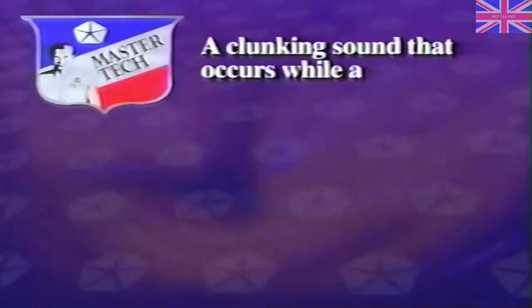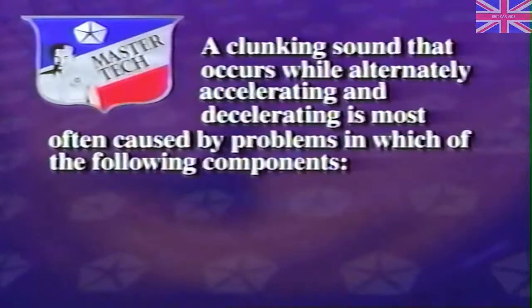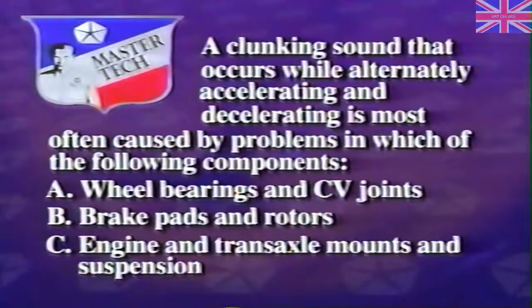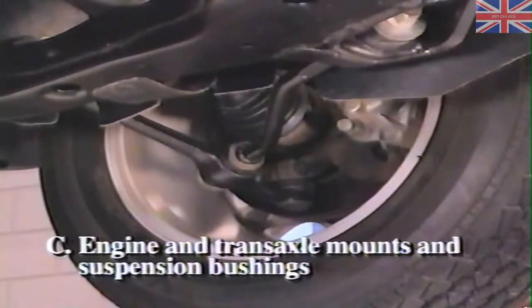A clunking sound that occurs while alternately accelerating and decelerating is most often caused by problems in which of the following components? A, wheel bearings and CV joints. B, brake pads and rotors. Or C, engine and transaxle mounts and suspension bushings. The correct answer is C. If a clunking sound occurs while alternately accelerating and decelerating, you should inspect the engine and transaxle mounts and also inspect the suspension bushings.